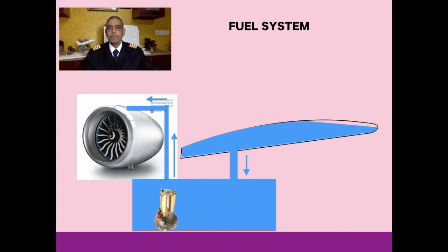And I just want to give additional input that there is an interconnect duct between the two wings, so that even if there is an imbalance in the flight between the right and the left wing fuel tank, which could be determined in flying the plane in terms of rolling moments, it is possible to equalize the fuel levels in both the wings.